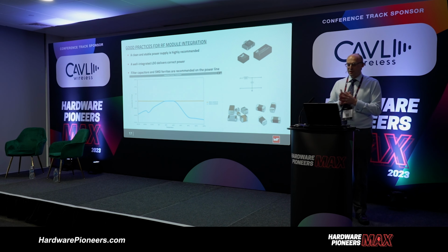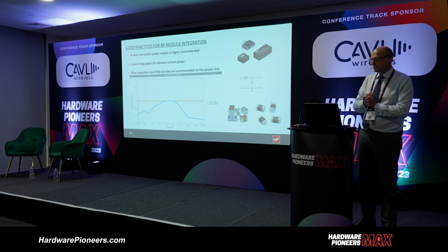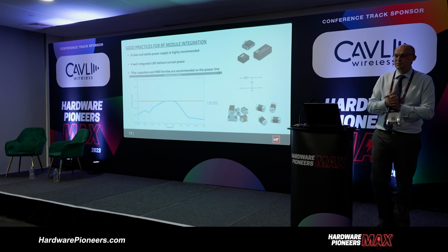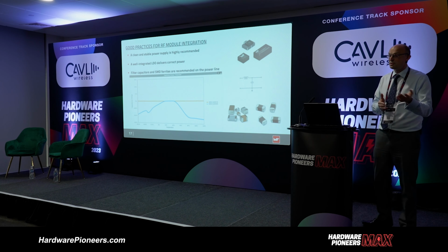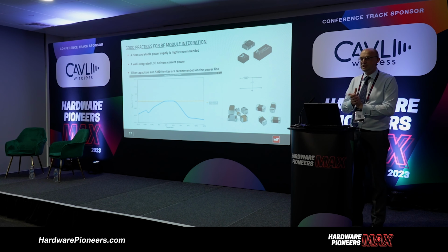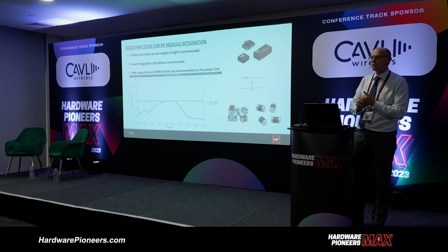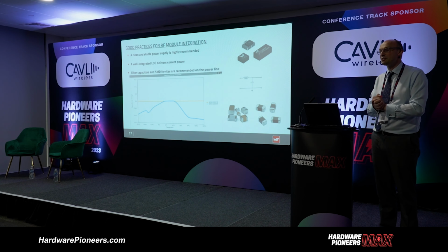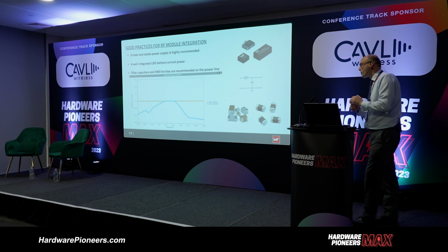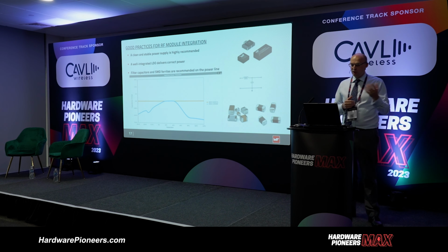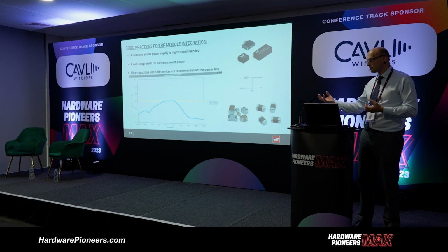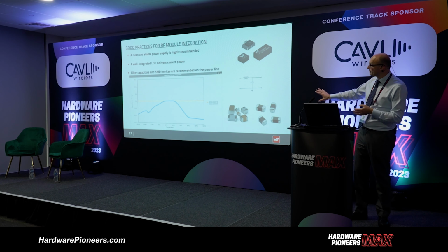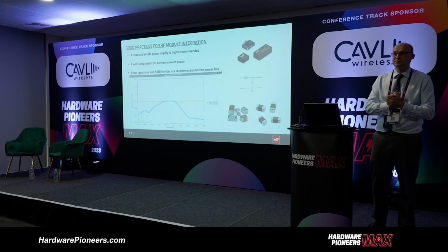The thing with an RF module is that you're certifying it across its operating temperature range. That may be from -40 to +85, could be from 0 to 70 degrees. But what do we actually certify? When we're doing the testing, what temperature is it? I guess roughly what we're sitting in at the moment, 20, 25 degrees. However, certain components within your host product, as well as the radio module itself, are temperature dependent. An example here will be what seems to be quite simple, multi-layer ceramic capacitors.